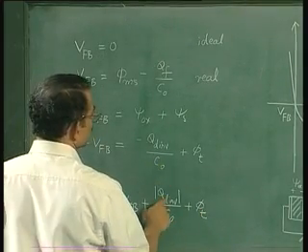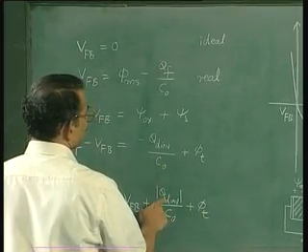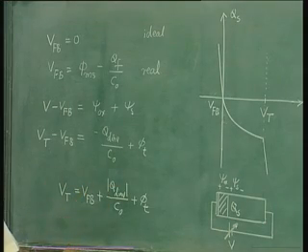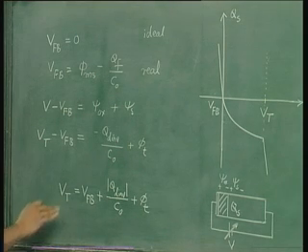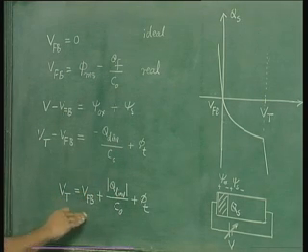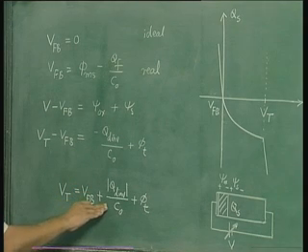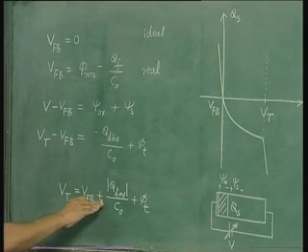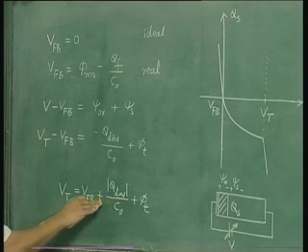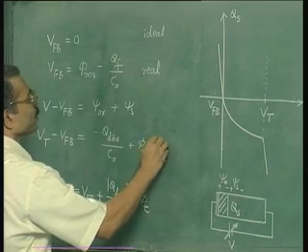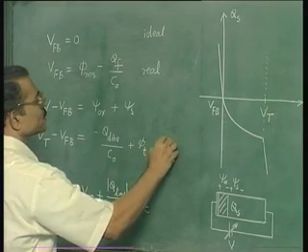It is useful to write this charge in terms of the modulus, because then we will find that we can write the equation very easily for n-type capacitor also. So we can write this equation and then show that just the signs change to negative signs here to account for a capacitor which has an n-type substrate. So here this is p-type substrate that we must note.